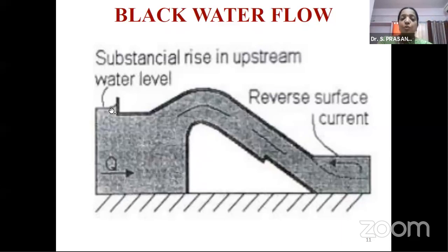Now, as the level of the water reduces, you can see the normal action of your weir or deflected flow or drowned flow or air partialized flow can still continue. That means there is nobody who is going to operate the gate over here in order to dispose of the water. It is just doing it on its own, and it is completely self-priming. So any small reduction will again encounter the previous cases. Based on this sort of functioning, siphon spillways have gained a lot of importance.